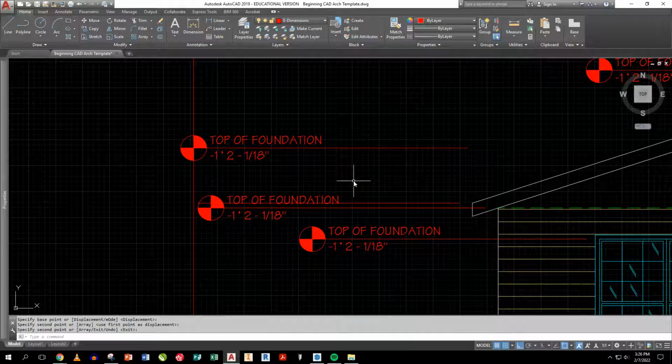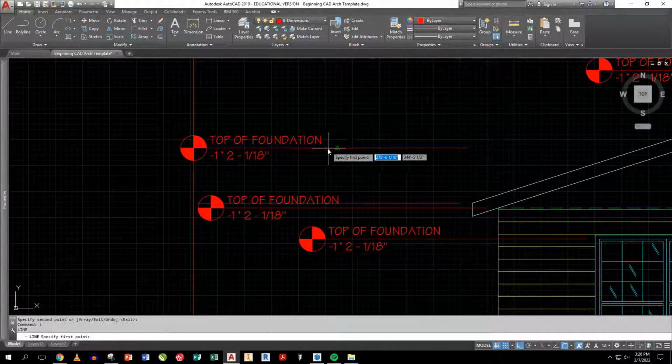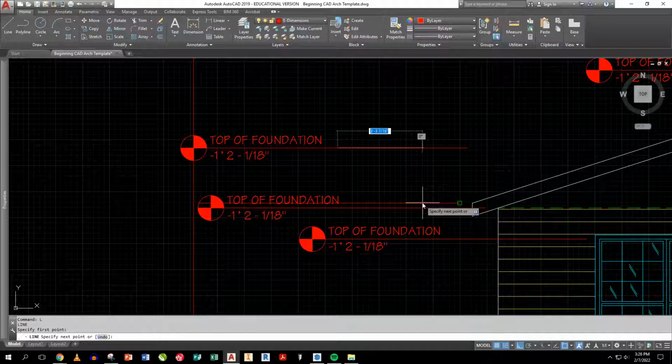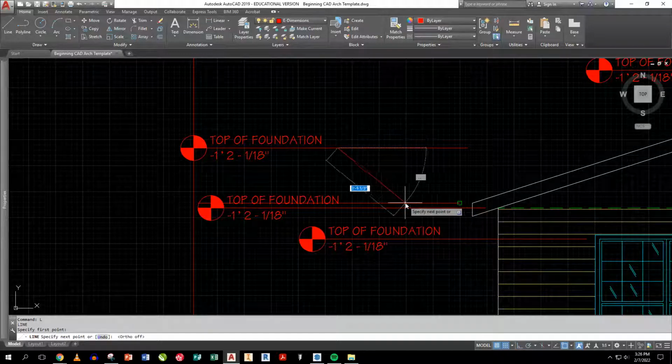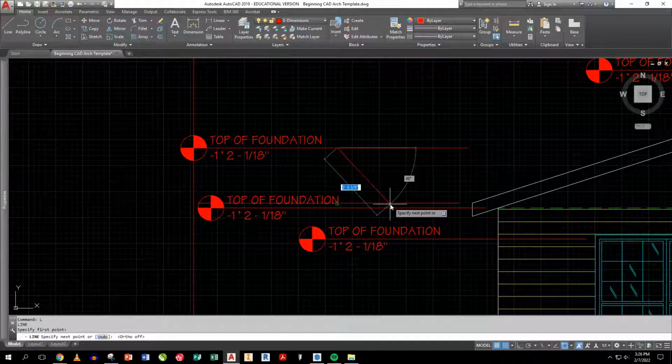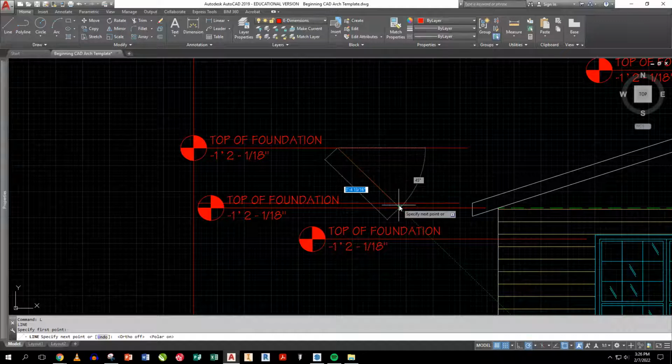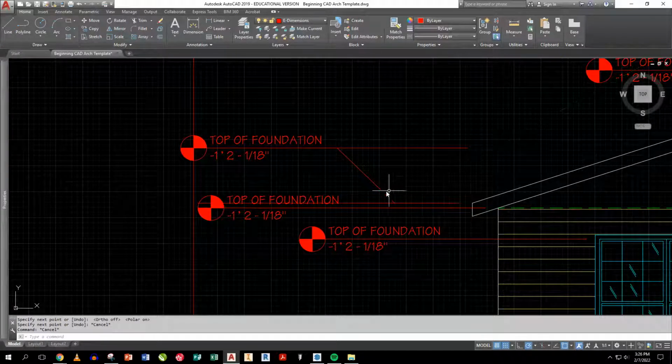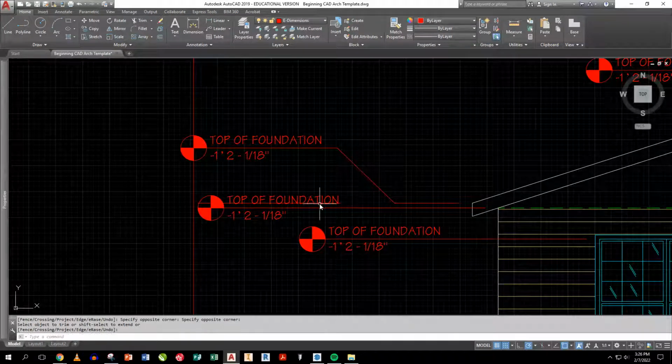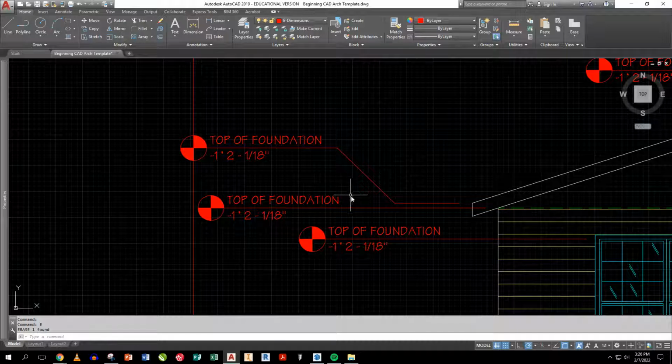And then just literally draw a diagonal midpoint here. And I'm going to go turn off that. I want 45 degrees down. So my F10. Okay. And then I just simply use the trim button to get rid of that and that, and the extra line work I've got here. Okay. That way everything reads clean right there.